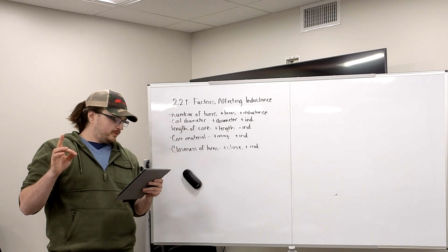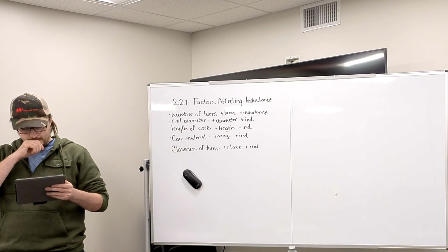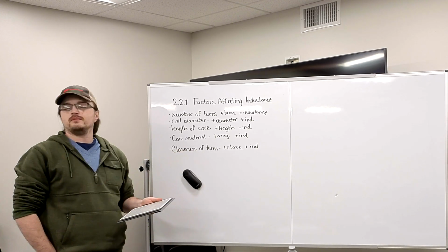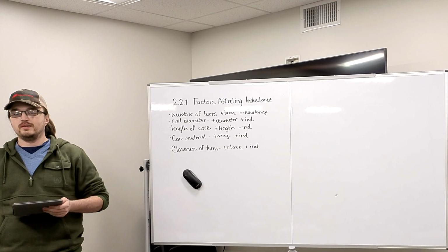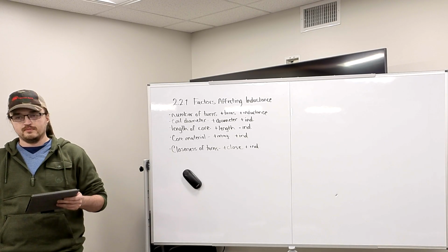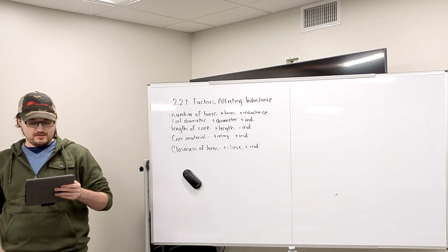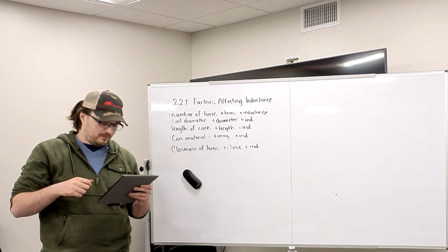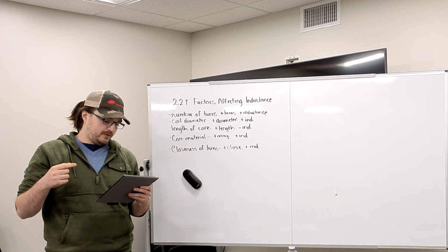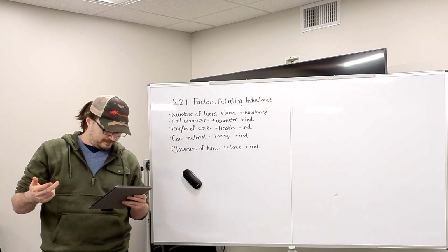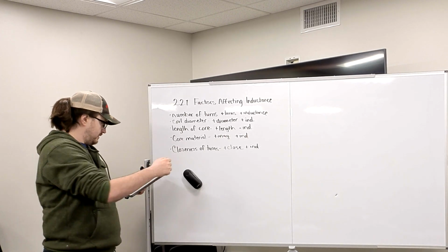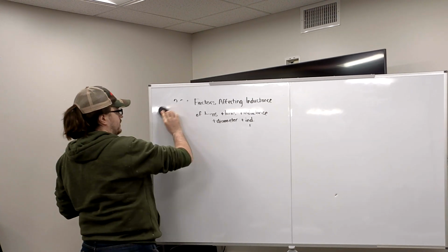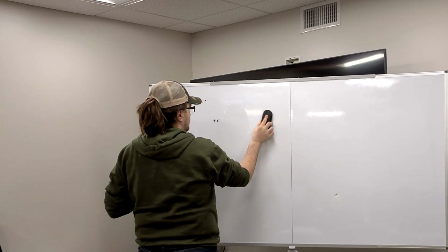All right. One more thing. Winding the coil in layers. Plus, more layers is more inductance. So more layers make a greater effect of magnetic field on the conductor, which results in more inductance. Figure 11 has illustrations of this stuff. If you want to look more into it, I feel like it's pretty straightforward.